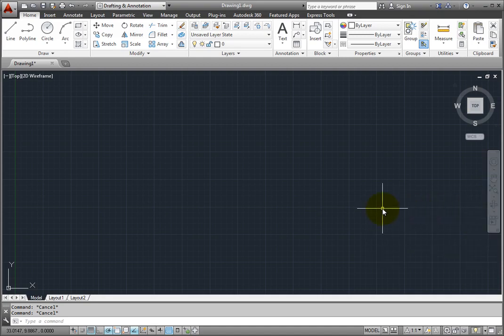In the lower left corner of the viewport is the UCS icon, which displays positive directions of the X, Y, and Z axes. Across the bottom of the drawing window are the Model and Layout tabs. You work in model space when creating actual geometry, and switch to one of the paper space layouts to produce sheets of paper on which you will print or plot your work.